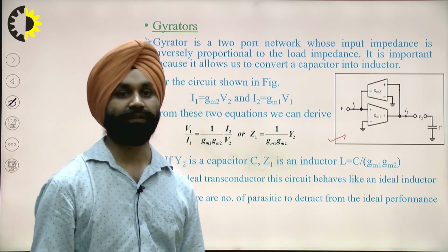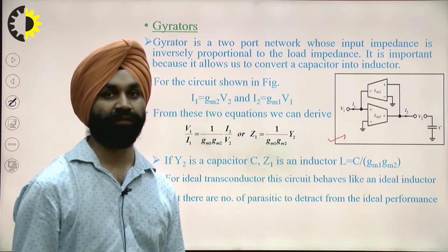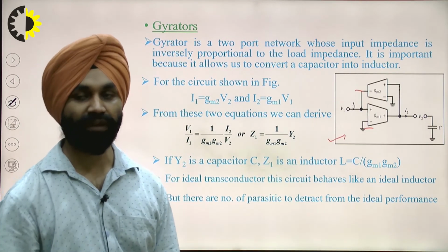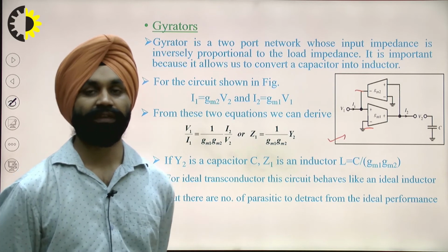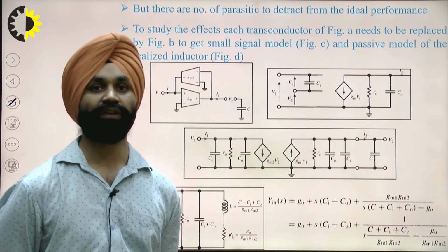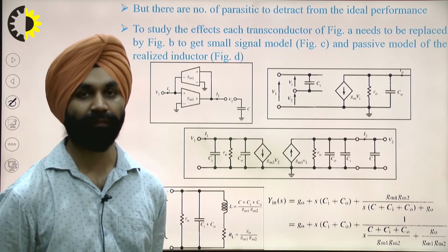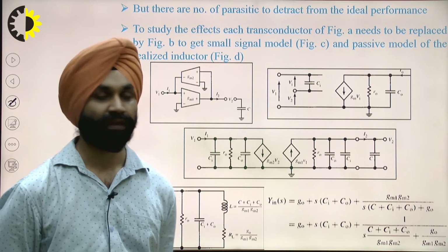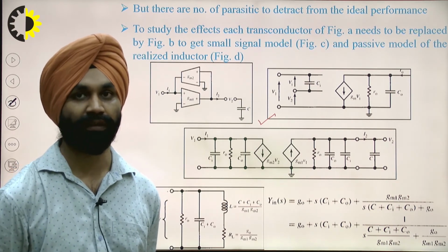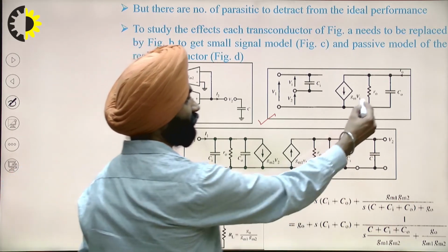However, this is not the case. There are parasitic capacitances which always interfere with the capacitor C. As we have seen in the previous cases, there is a model which gives the internal capacitances. So if we include the internal capacitances of the MOS, we have the model we designed in the previous case, with passive resistances and capacitors.